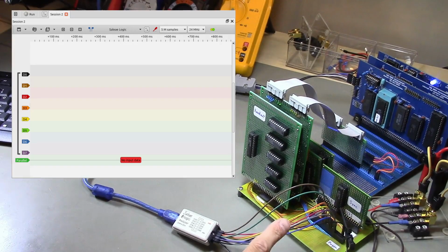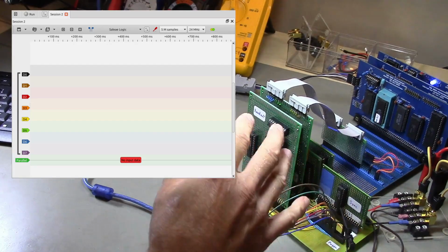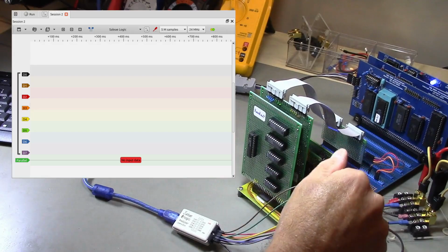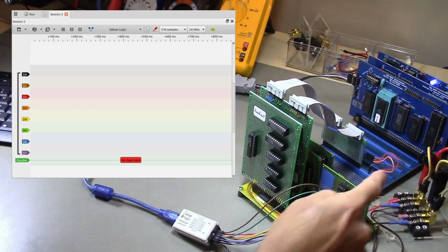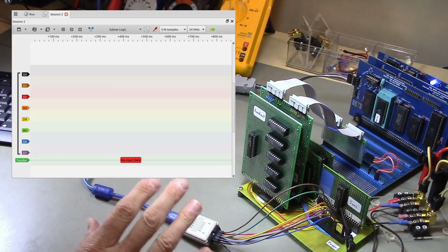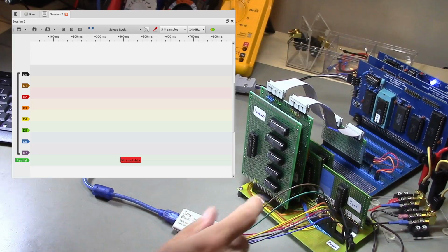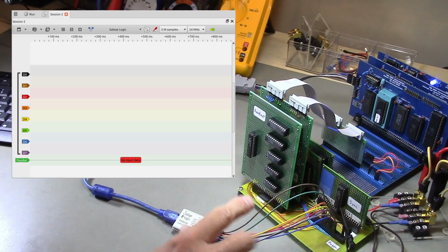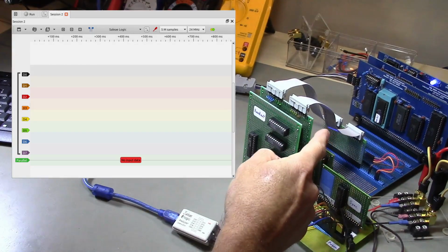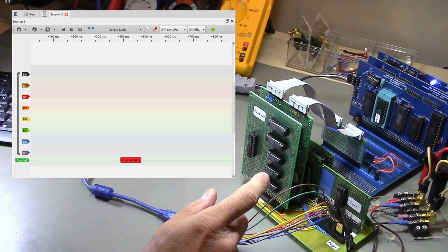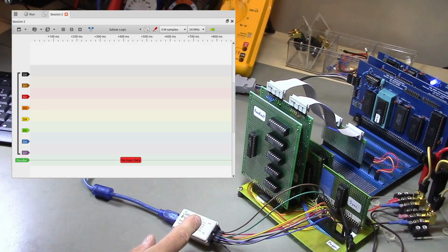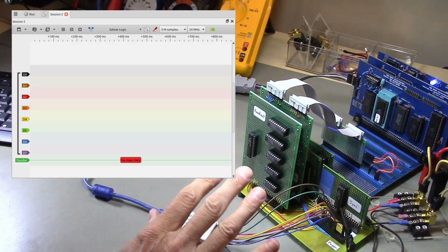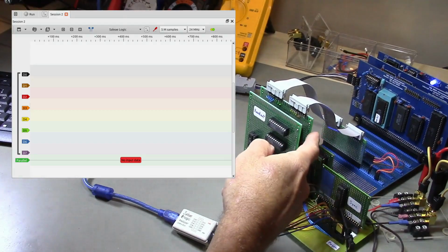And this is obviously the data that the pixel generator is going to render into pixels and color values that will be sent to the output module, which is not installed right now. All right, so I have run the VRAM test program, and that just puts increasing arbitrary byte values into each bank of the video memory. And so what I am hoping is that if I capture data using the logic analyzer, I should see those incrementing bytes that are coming out of the VRAM.